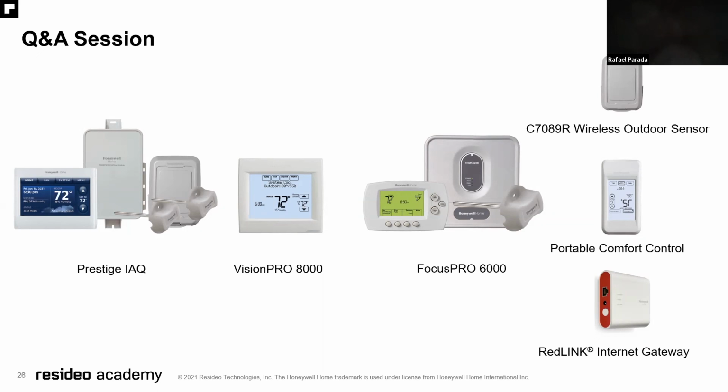So we can recommend the homeowners to change the time on the schedule. If they want to have, for example, 70 degrees at 7 a.m., they should set the schedule probably at 6 a.m. for 70 degrees. So the thermostat starts the system at 6 a.m. and then the heat ramp starts without any override on the droop stage or the upstage timer.